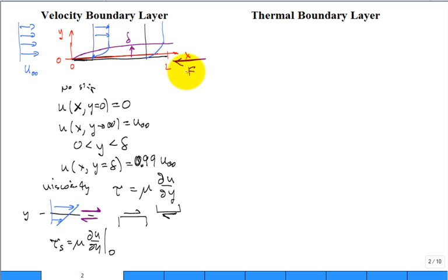So what we do is we're very much interested in the shear stress at the surface. Sometimes they'll put C sub F. It's dimensionless shear stress at the surface. So this was defined as the shear stress at the surface divided by something that gives it a dimensionless quality. So in SI units, shear stress is just like a pressure, force per unit area, isn't it? I need to divide by something that has units of force per unit area. What do we divide by?